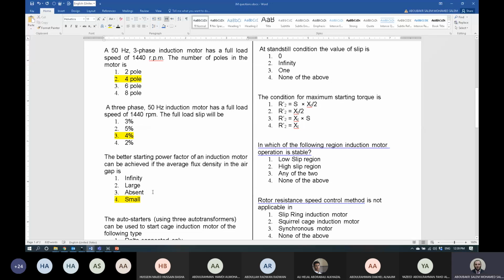because this is not the case at full load, because at full load you will have something extra due to dynamics, and this is going to increase the resistance. Right? Even the flux is high. Due to operation with high value of flux, even if you are close to saturation or before saturation by a small value. So at full flux or high value of flux, even the flux is high and the inductance is high, slip will be very small.